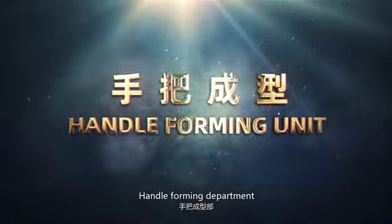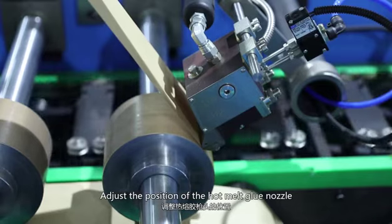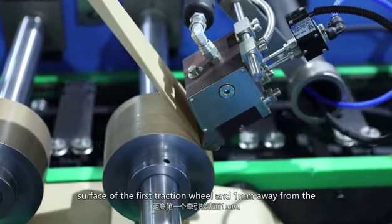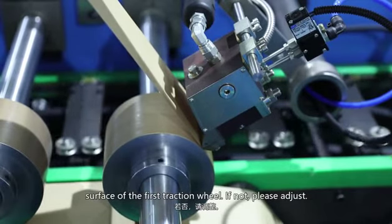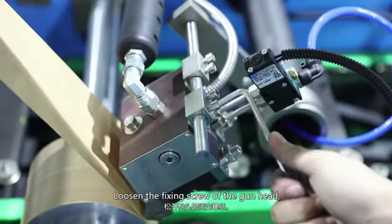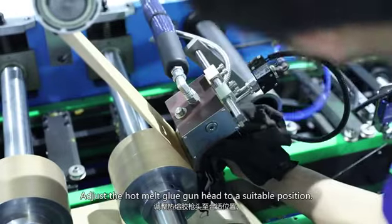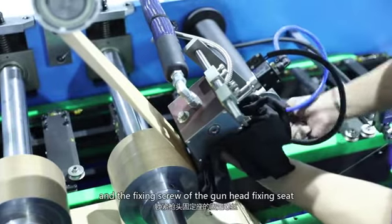Handle forming department. Adjust the position of the hot melt glue nozzle. The tip of the hot melt glue gun should be perpendicular to the surface of the first traction wheel and 1 mm away from the surface of the first traction wheel. If not, please adjust. Loosen the fixing screw of the gun head and the fixing screw of the gun head fixing seat. Adjust the hot melt glue gun head to a suitable position. Tighten the fixing screw of the gun head and the fixing screw of the gun head fixing seat.